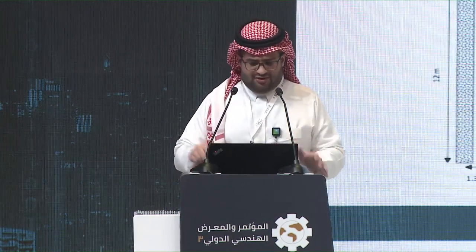We did some cost analysis, and we ended up that having the soil improvement with the stone columns approach is more efficient in this particular project. It is the best technique due to its flexibility with soil type, depth of improvement, cost, and time as well.